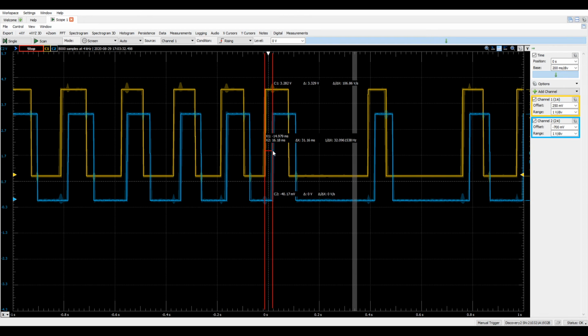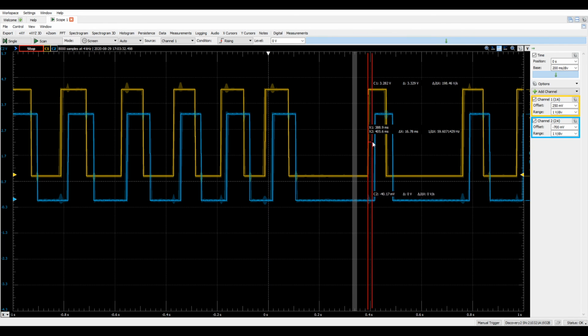Okay, I'm going to do that one more time in here. And there you go. Well, I guess I measured a little bit longer here. This one is from here to probably here. It's about 28 milliseconds. You get the idea. It's usually between 20 and 30. You're not going to get 31 or something. Whatever I did, I did it in the wrong position, but you get the idea. All of them are not exactly the same, but they're within spec. This one is 27. And the blue output is usually what we get as the debounced output.